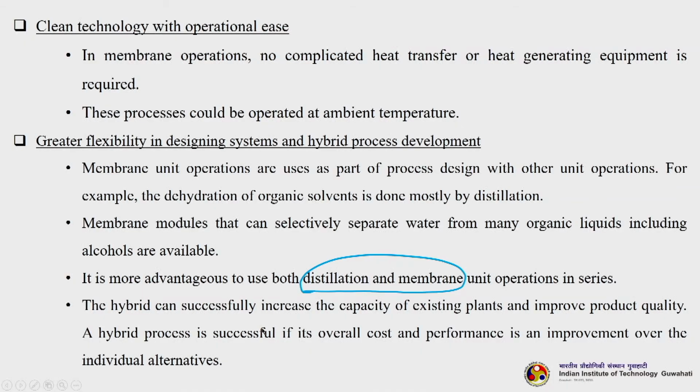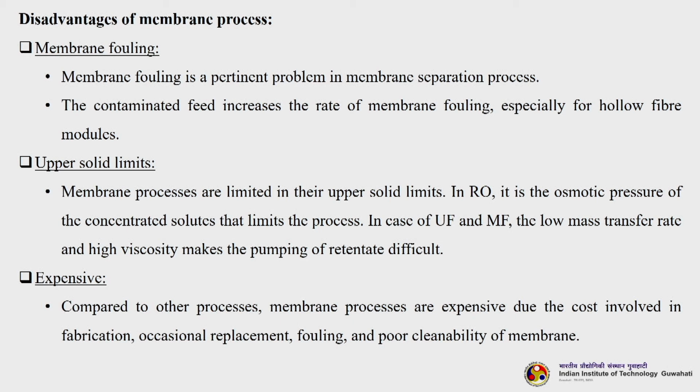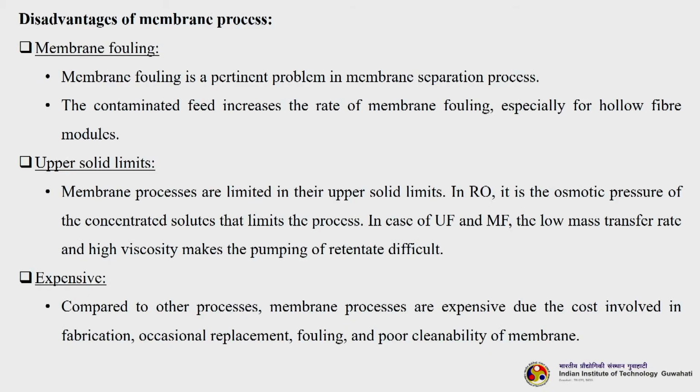So, next is disadvantages of membrane systems. We understood what the advantages are. It is not always that membrane is a win-win situation for any prevalent separation need. There are certain disadvantages. The first one is membrane fouling. Membrane fouling is a pertinent problem in membrane separation processes. The contaminated feed increases the rate of membrane fouling, especially for hollow fiber modules.